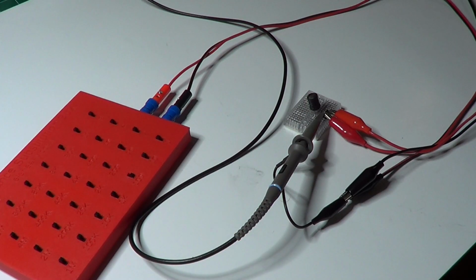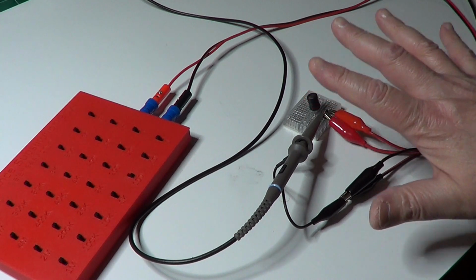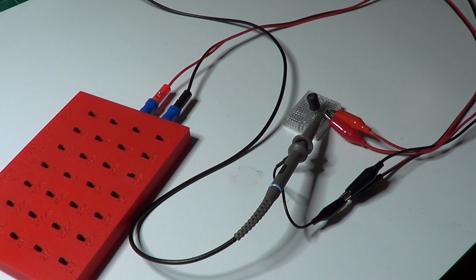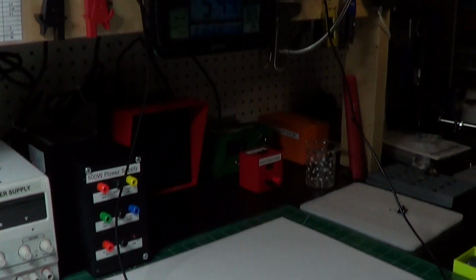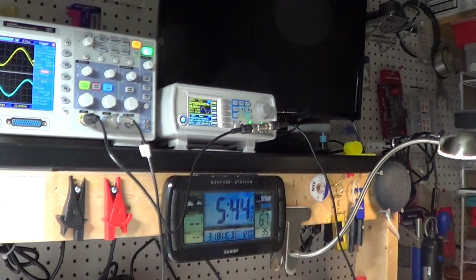Let's do one more test now. This time we will try to visualize the lagging of the current to the voltage. We will try to see if it is actually 90 degrees. The circuit to do so is exactly the same as the previous test. In fact, we want to measure again the current flowing in the inductor, so we need the channel 2 of the oscilloscope connected in parallel to the resistor. What changes is the input voltage from the generator, that now is a sine wave, as you can see here.